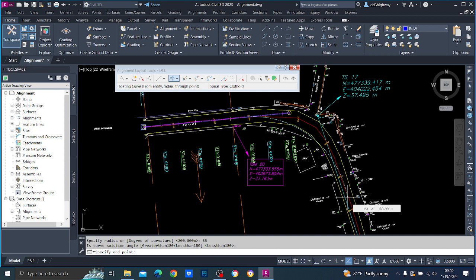But that depends, because you see, highway design is an art, right? So there is no right or wrong. You have to take decisions depending on the site conditions. Just think that this house is some old house, and it is going to collapse or something, then of course you can acquire it. But if this is a 5-story building, then you cannot acquire it. So you have to take the decision depending on the site condition.